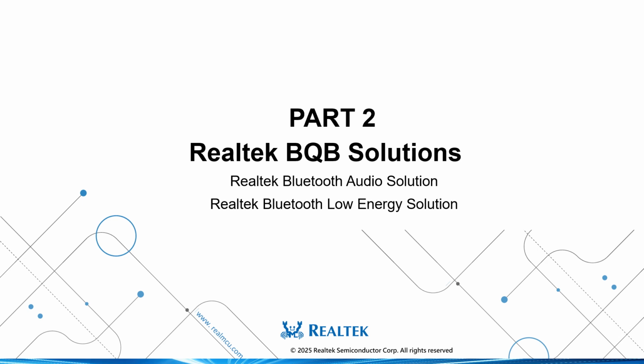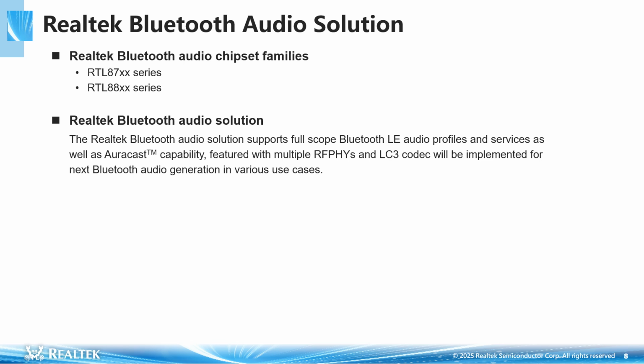Part 2. We'll introduce the Realtek BQB Solutions, including Realtek Bluetooth Audio Solution and Realtek Bluetooth Low Energy Solution. The Realtek Bluetooth Audio Solution supports full-scope Bluetooth LE audio profiles and services as well as Auracast capability, featured with multiple RF-PHYs and LC3 codec will be implemented for next Bluetooth audio generation in various use cases.